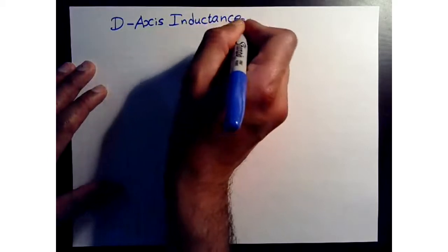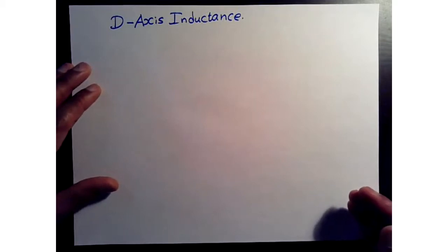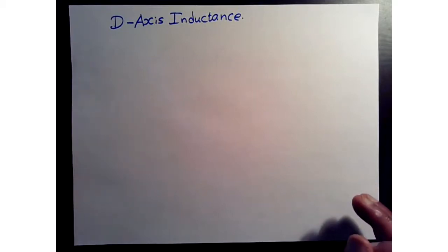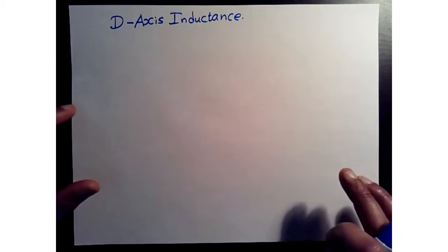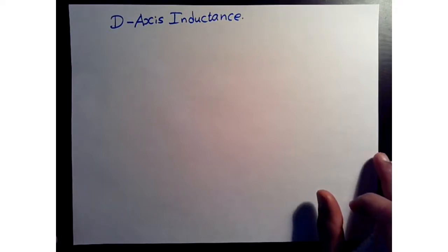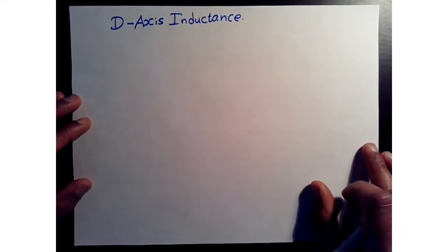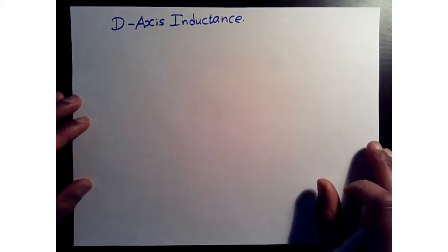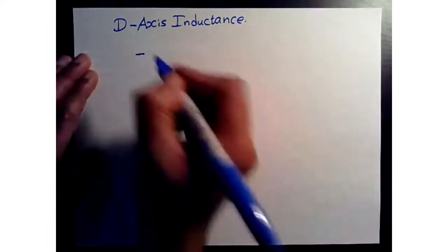Now, keep in mind, there are LCR meters that you can use to measure d-axis inductance, but some of them are very low current. And the problem with them is you are not capturing the full flux linking through all the winding and the material, because there's no flux building up when you measure inductance. So you have to be a little bit careful when you use those measurements. Sometimes they are inaccurate depending on the current and the design of the machine.